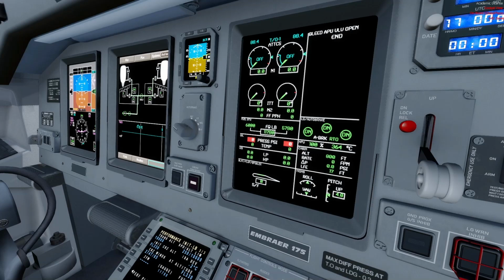One thing to note is if at any point the ice condition has been detected during flight, the airplane basically says, okay, we did accumulate some ice, so here's anti-ice, Mr. Captain and FO. We would try to get rid of as much ice as we can, but the assumption is we're also accumulating ice in other parts of the airplane that are not heated, for example the tailplane or the trailing edge of the wing or the upper surfaces. So remember, the surfaces that are actually heated are very, very small compared to the entire airplane.